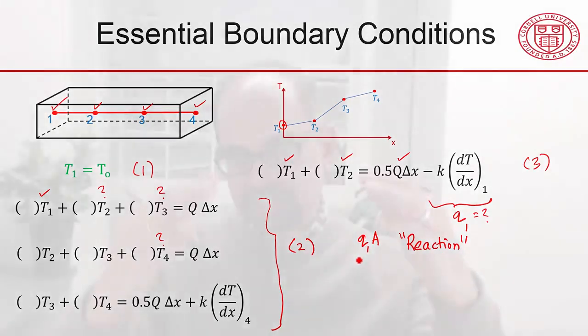And this three-step process is very general, and any finite element solver is going to use this three-step process. Step 1 and step 2 are necessary, and step 3 is highly recommended to check on whether your solution satisfies fundamental physical principles such as energy conservation or equilibrium.